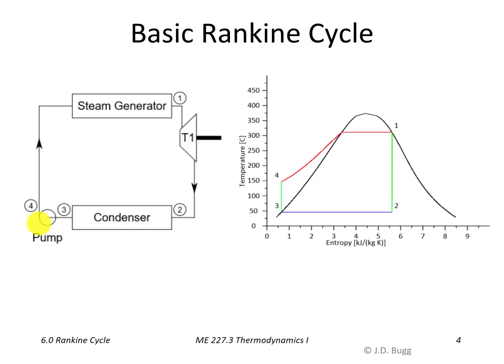Now we want to see what this looks like on a TS diagram. So this is the same TS diagram as before, just with a liquid pump instead of with a compressor. Now a couple of things about this TS diagram. First of all, it is drawn to scale. The saturated liquid and saturated vapor lines here are plotted using real data from your textbook, and we see now that instead of having a compression process completely inside the liquid vapor region, the condenser has now condensed all of the liquid, so we have 100% liquid, saturated liquid line, and then we compress.